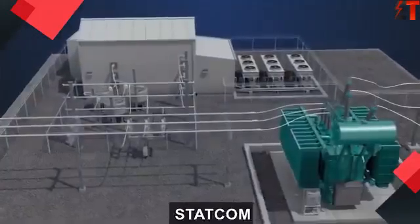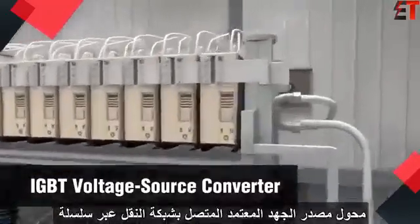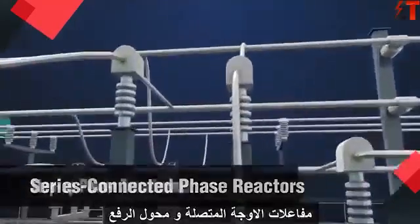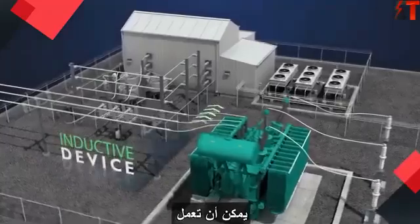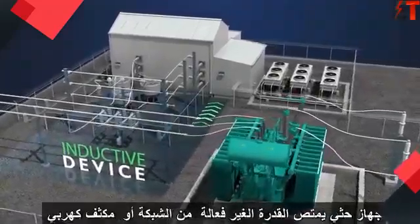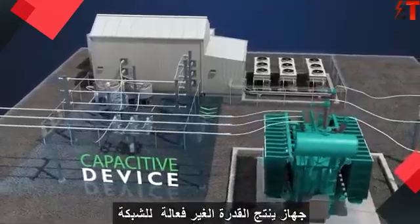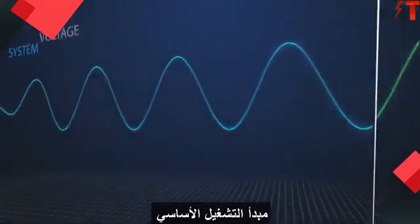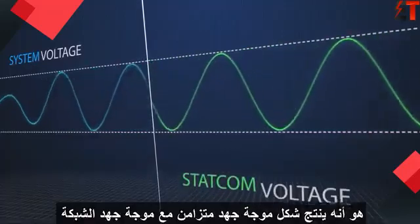A modern Statcom is a shunt-connected device that is comprised of an IGBT-based voltage source converter, connected to the transmission grid via series-connected phase reactors, and a step-up power transformer. A Statcom can act as an inductive device, absorbing reactive power from the grid, or a capacitive device, producing reactive power to the grid. The basic operating principle of a Statcom is that it produces a voltage waveform in sync with the transmission system voltage.